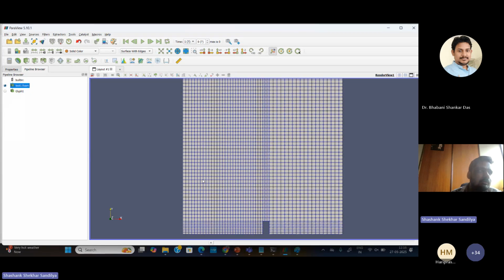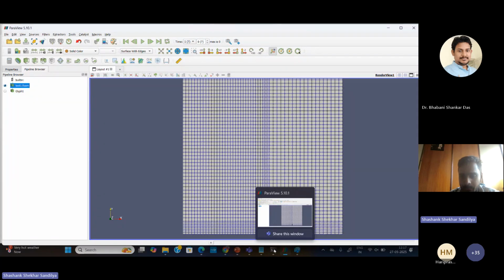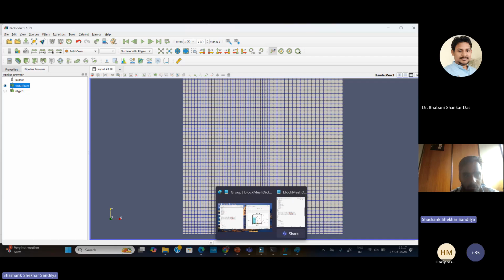See the fineness in the left-hand side and post mesh in the right. You can see the fine mesh here in the left hand side and coarse mesh in the right hand side. Because I have reduced the grading to 0.8 in block 0 and block 2. Actually, not mesh size. I have compressed the blocks in the right direction. So here in left side, if you see, here the cells are coarser. Now it is getting finer towards the obstruction. Because this is our block 0 and block 2. We have done it to only block 0 and block 2. Others are as they are. So this is how we modify our mesh. We create our geometry. So the best way is to find a problem identical to your problem and start with that and make modifications in that case.